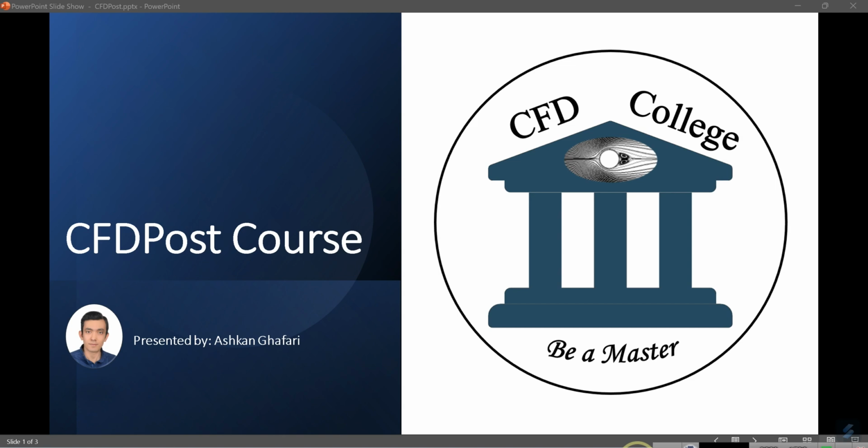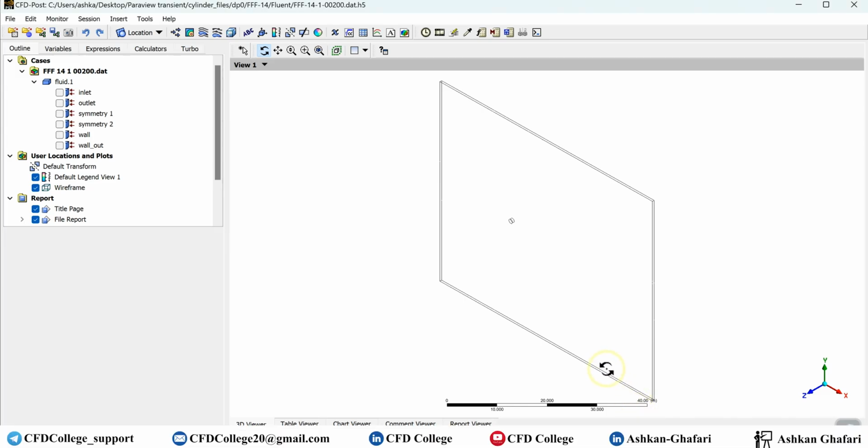And let's get started with this tutorial. In this session, I'm going to show you how you can generate streamlines in 2 and 3 dimensional domains of your CFD results. You can use streamlines to study, to examine, and to show the flow field in your CFD domains. In this video, I will show you how you can do it.